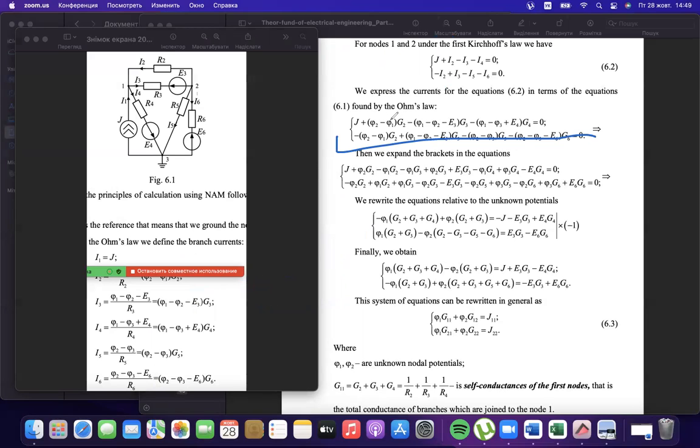Firstly, multiply all potentials by all conductivities, enclose in brackets, and then we group parts of the equation by the same potential. Because in the previous step they were grouped by conductivities, with conductivity outside the brackets. But then we transform the same equation by the potential. Inside brackets will be conductivities, but outside the potential.